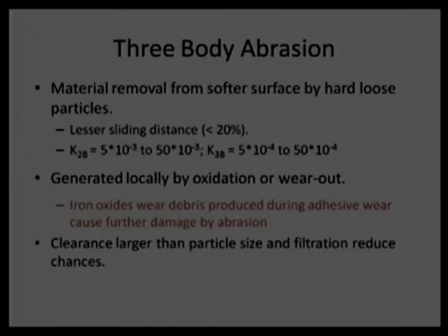Or we say adhesion is leading to the abrasion, three body abrasion. Interesting thing is that if the clearance between two surfaces is larger than the particle size, then this third body abrasion will not cause much damage.